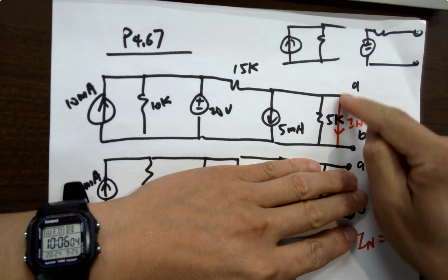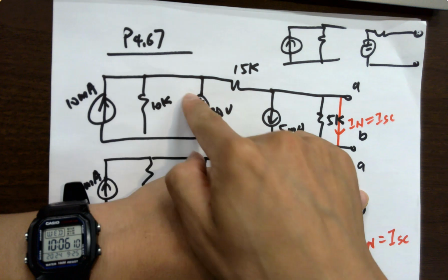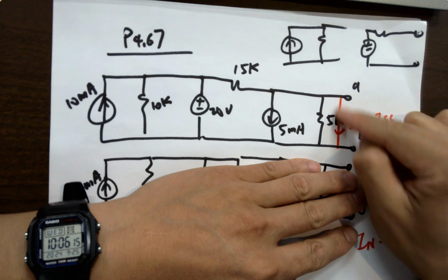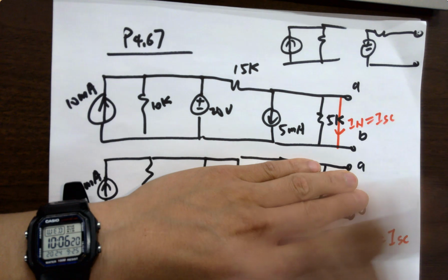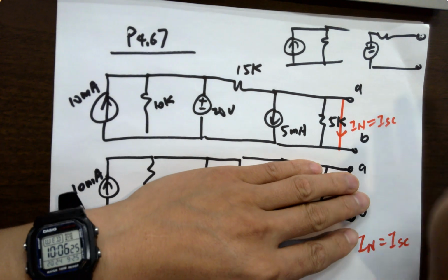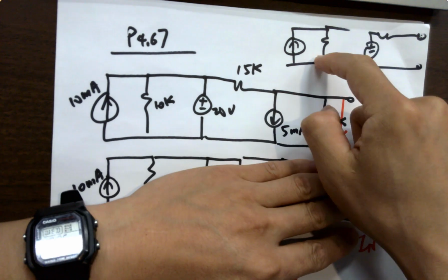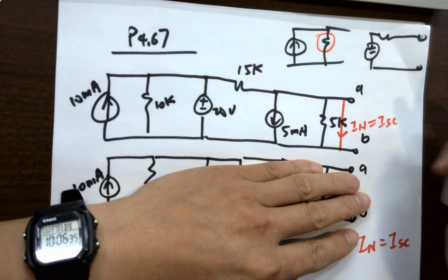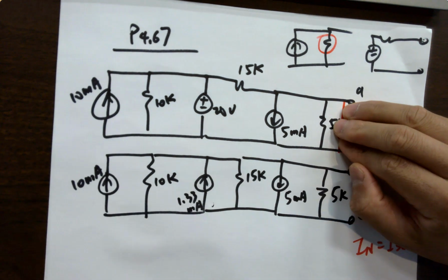So how to find this current? We have learned nodal voltage, mesh, whatever you have to use, okay? You should be able to find the current here, without any problems. All right, good. No source transformation. Draw a wire here, that's the definition. Why do you draw a wire? That's the definition. Okay? So if you want to convert the original circuit to here, to the Norton equivalent, remember we have learned how to find this resistor, right? We remove the load and look backwards. No problem on that. Okay?